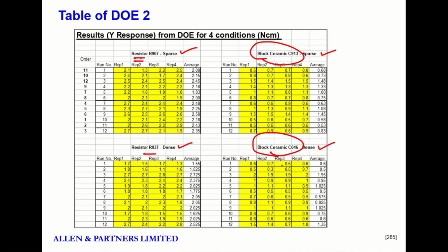All of this data was collected separately, and then we end up putting all of this data together in one big data table and analyzing it using the marginal means. This particular technique was marginal means only. That's all we used to do this. So an L12 with a graphical analysis and a robust element. And here's what we learned.